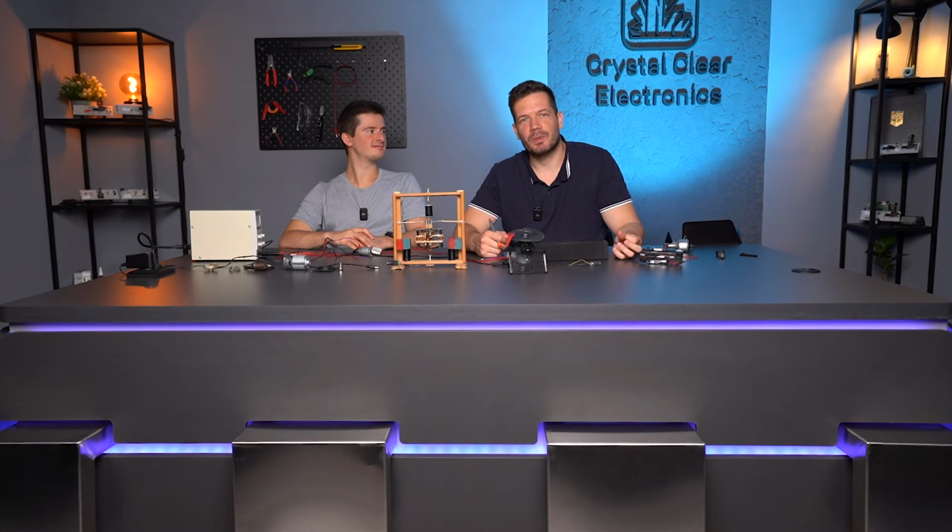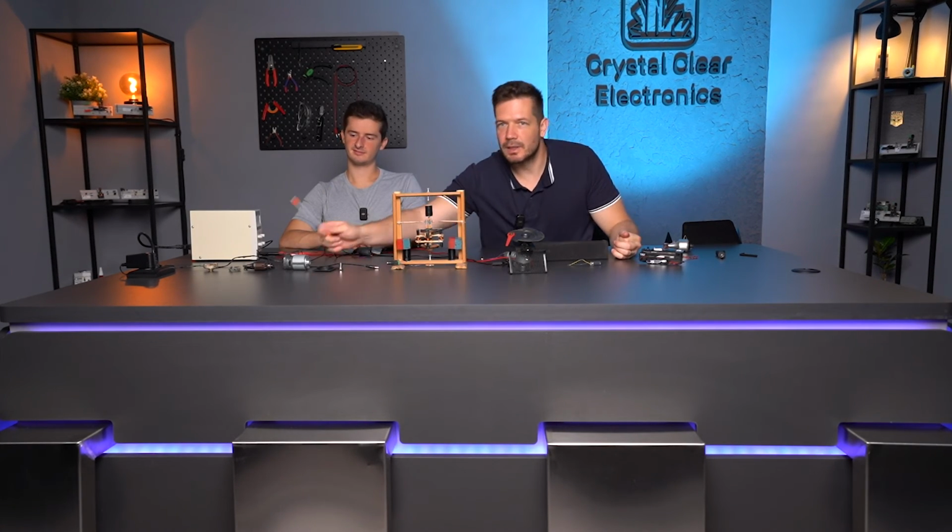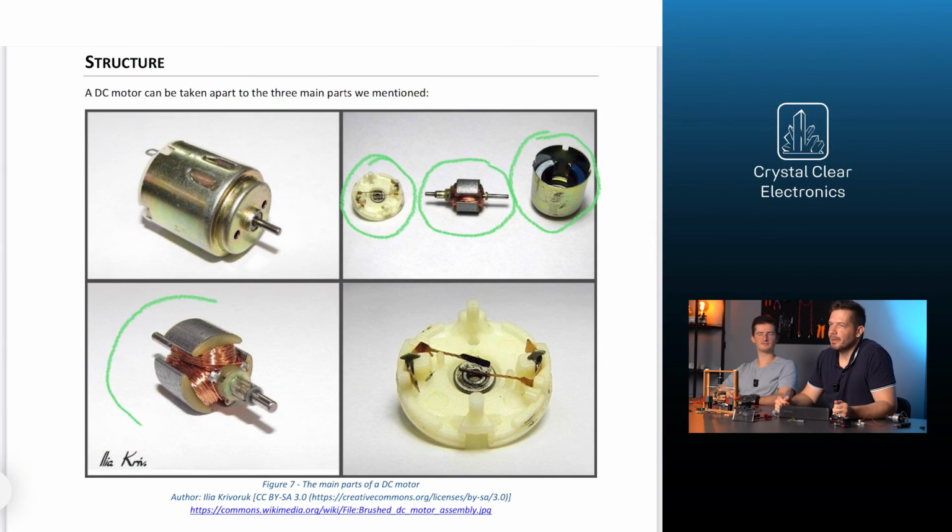Our next main part is the rotor, also known as the armature. The rotating part of the DC motor is typically made from ferromagnetic material. You can see it here. Copper conductors are wound in the grooves of the rotor. Again, iron has a role in concentrating the flux lines and making sure the conductors stay in place. The coils are connected to the commutator as shown in the figure.